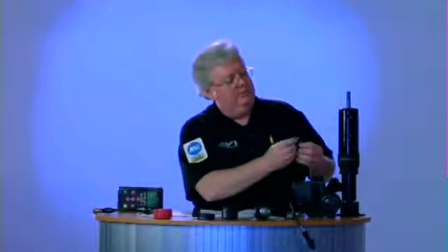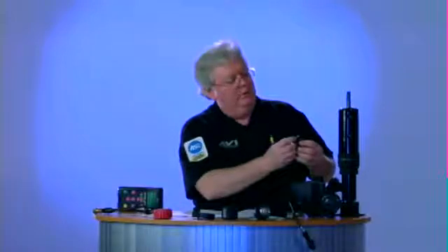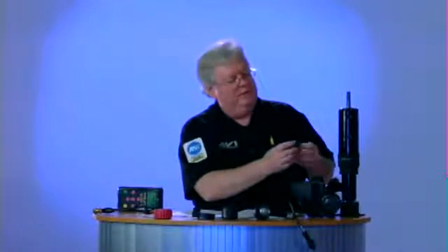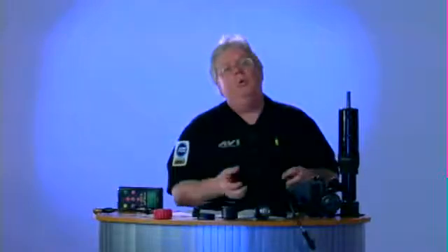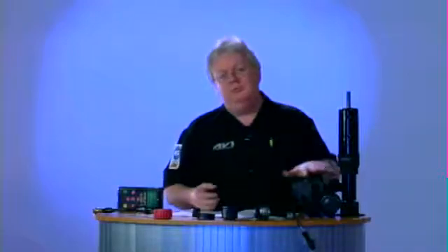Make sure you use the proper fluid. I started to say transmission fluid. Many power steering systems may use transmission fluid, but check to see what that manufacturer calls for their power steering fluid. This one says use approved fluid. Okay, we know that. Fill to proper level, do not overfill. It does not tell you what kind of fluid. So you want to check it out either in the owner's manual or in the service manual and see what kind of fluid this particular pump and reservoir would need.